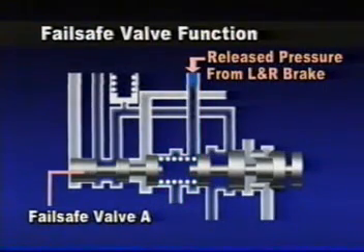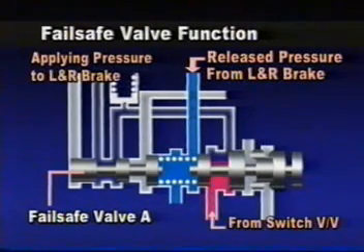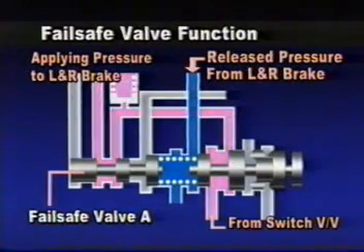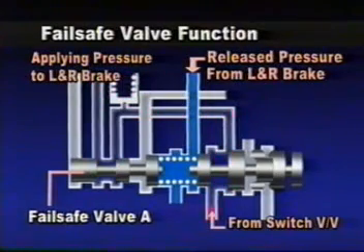When the rear gear is selected in neutral range, oil pressure of low and reverse brake moves out of the brake rapidly, which has been supplied in neutral range. Almost at the same time, oil pressure of low and reverse is supplied to low and reverse brake rapidly, which has been supplied with the switch valve.